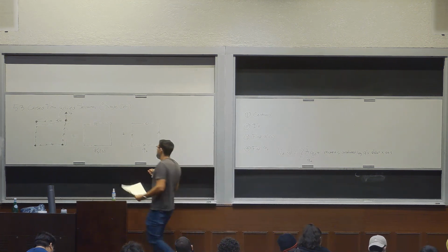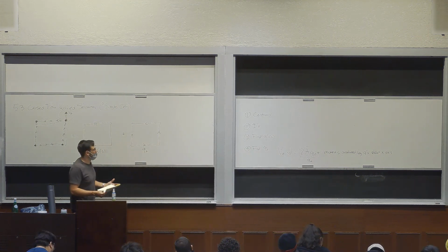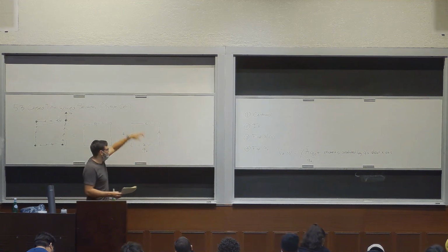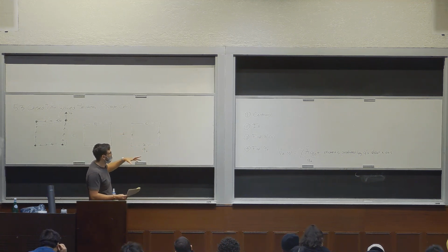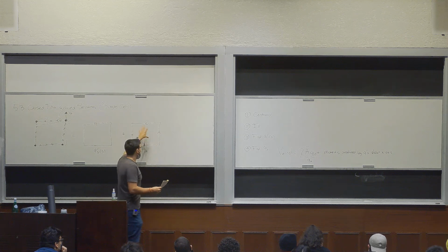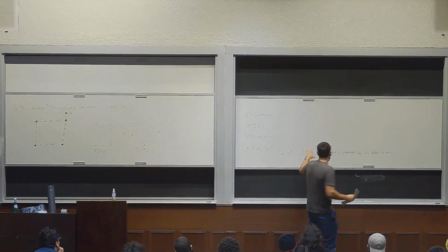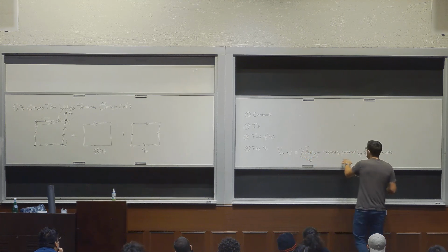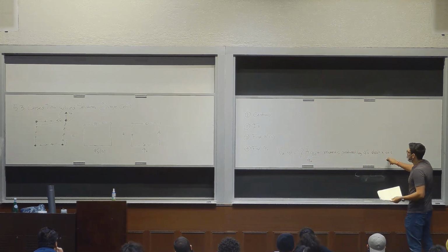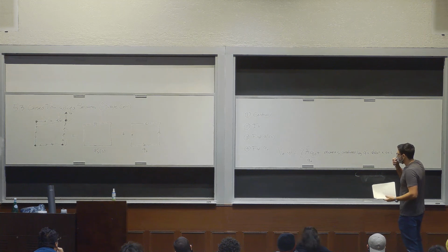If you guys remember from the torsion chapter, that's the equation for a constant shear flow around a closed section: 2 times the area enclosed times that shear flow. They'll give you a torque. And then also the moments produced by the Q's about the x-axis.